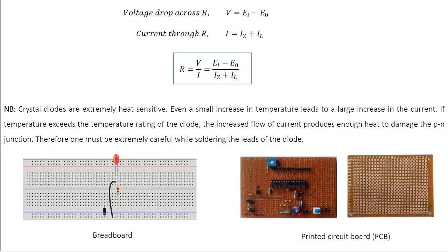So that's about the discussion on diodes. Before winding up, I want to tell you one important point. Especially when you are doing your practical experiments in your laboratory, you need to keep in mind that all crystal diodes are extremely heat sensitive. Even a small increase in temperature is going to result in a large increase in the current.